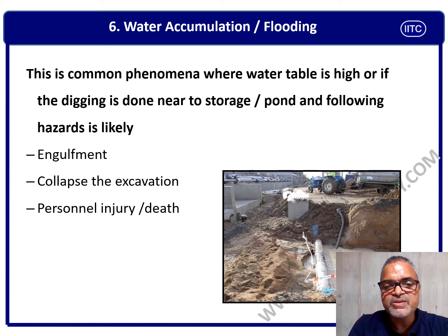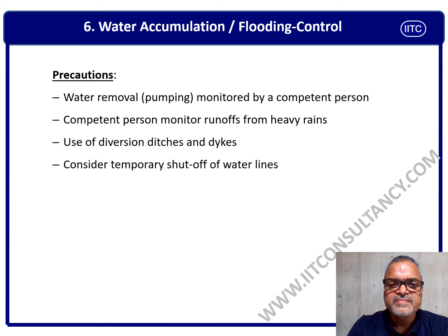So I mean to say that we, being leaders, supervisors, construction managers, safety engineers or managers, are responsible for managing the safety of our people. These are the precautions against water accumulation and flooding. The water removal or pumping system must be monitored by a competent person so that there is no accumulation of water inside the trench. The competent person monitors runoff from heavy rains. If you are doing excavation during the rainy season, heavy rains may flood your excavation, so the competent person must monitor that.